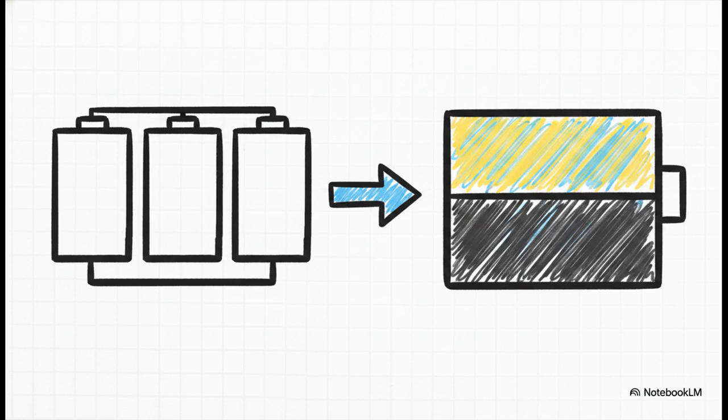Because these are sealed lead-acid batteries, discharging them all the way to 0 will absolutely ruin their lifespan. You can only safely discharge them to 50%. So we literally have to cut our number in half. That means our true usable battery capacity is actually 2,790 watt-hours.